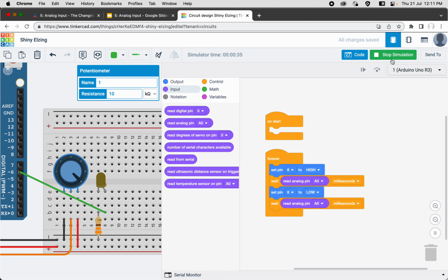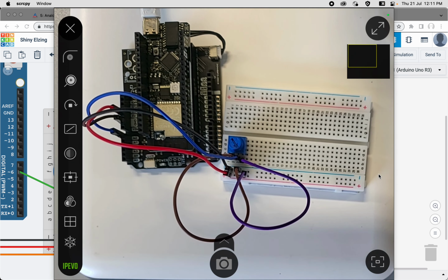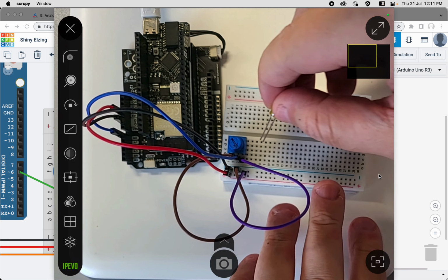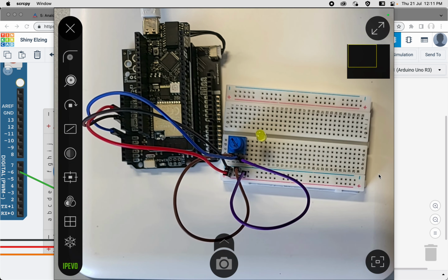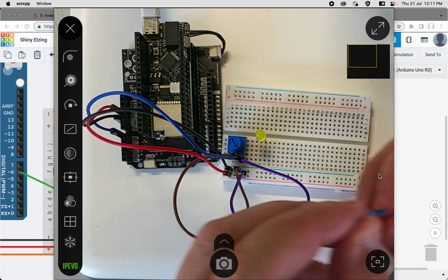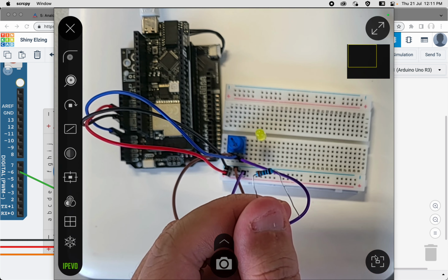We are going to try this out on the hardware. Okay, so I'm going to just plug in my LED, and then plug in the resistor. So make sure you are using a 330 ohm, not just any resistor. Always check, know which resistor you are using. So you are not doing those pull up, pull down resistor. You should be using the double orange. Okay, this one, the double orange.